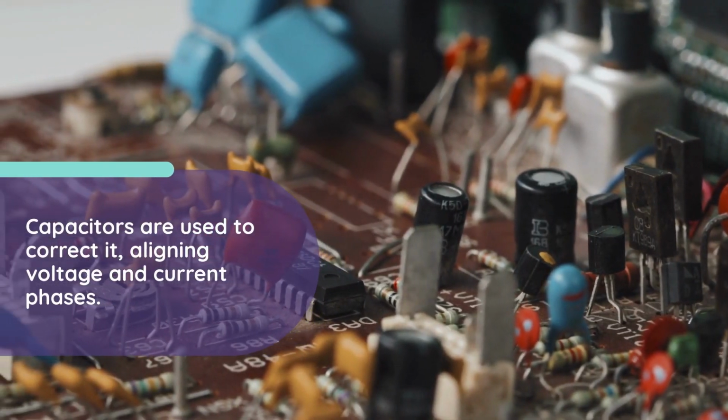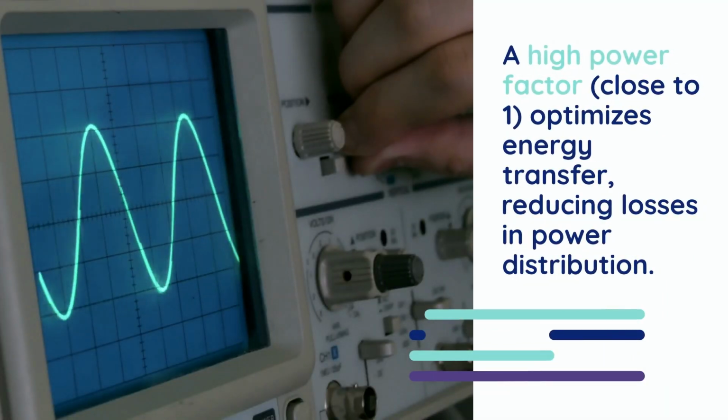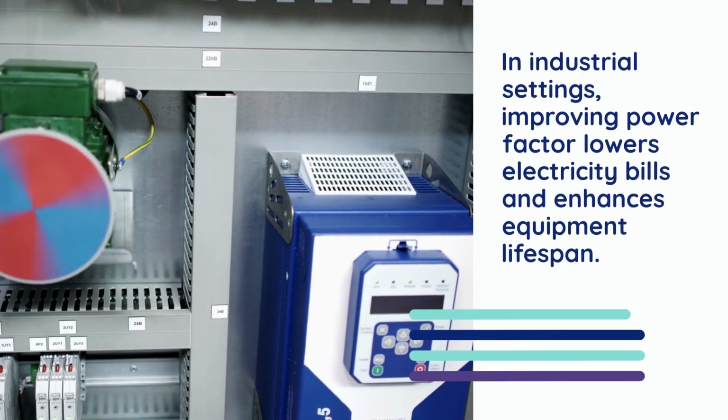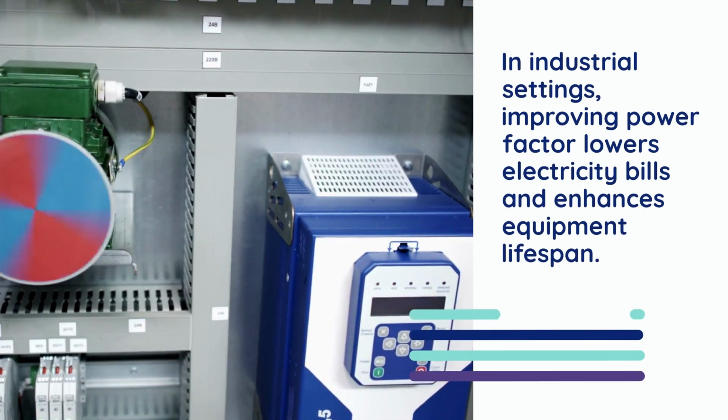Capacitors are used to correct it, aligning voltage and current phases. A high power factor, close to 1, optimizes energy transfer, reducing losses in power distribution. Utilities penalize low power factors as they strain grids. In industrial settings, improving power factor lowers electricity bills and enhances equipment lifespan.